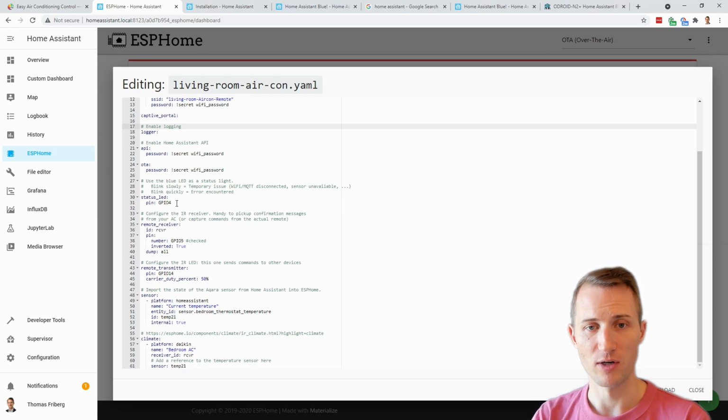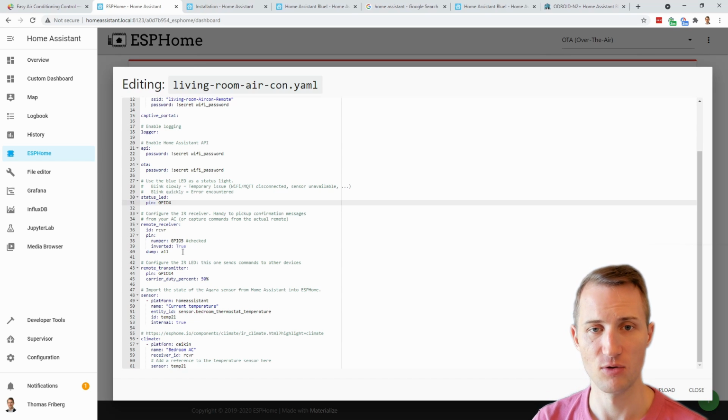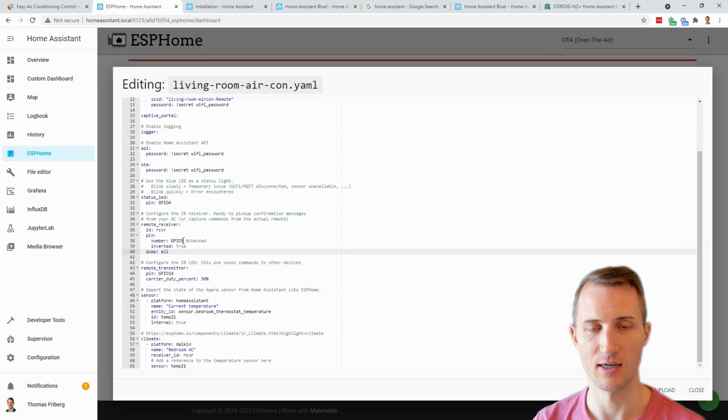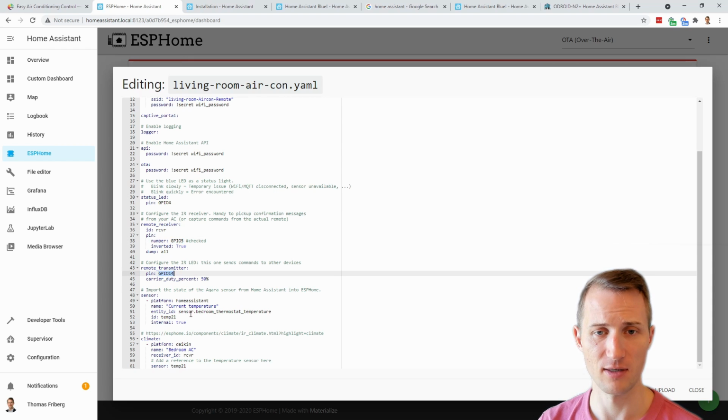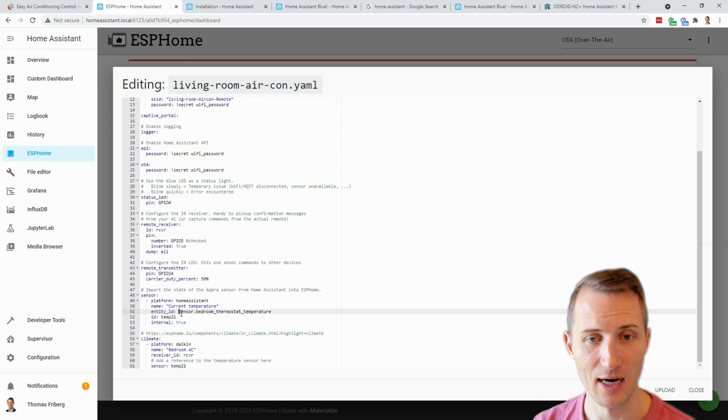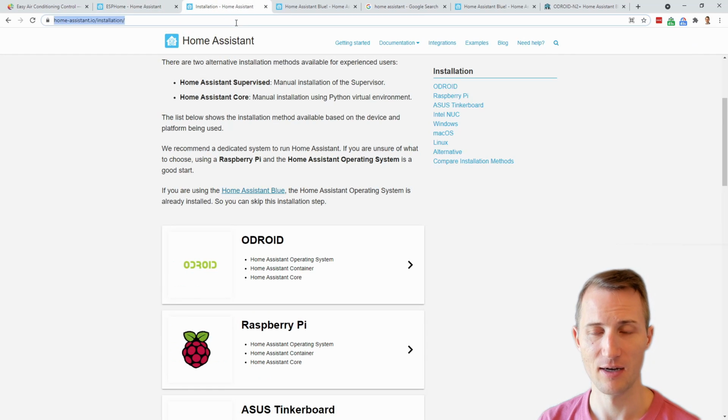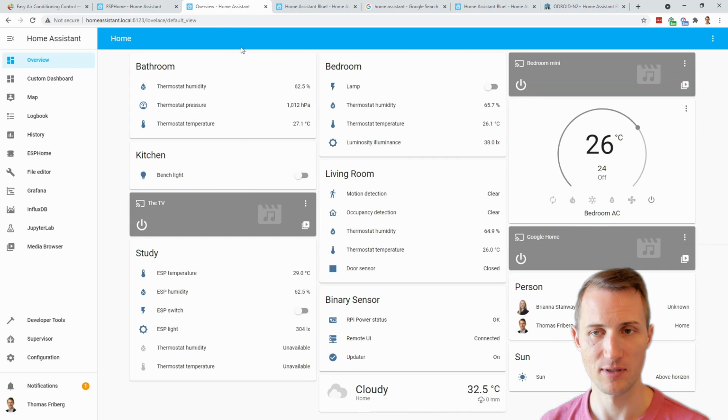Of course, you need to know what pins are connected to different things within this device. So that's where cracking it open helps. You need to follow the wire tracers to tell if the infrared LED is connected to GPIO4, or the fourth pin on the microprocessor. If not, then you might need to tweak the numbers that I've used there.